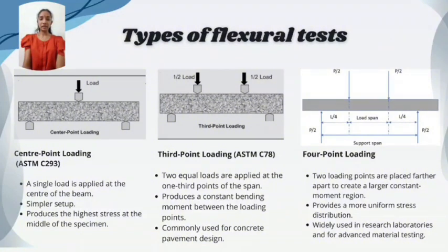And the third is 4-point loading. Two loading points are placed further apart to create a larger constant moment region. It provides a more uniform stress distribution and is widely used in research laboratories and for advanced materials testing.